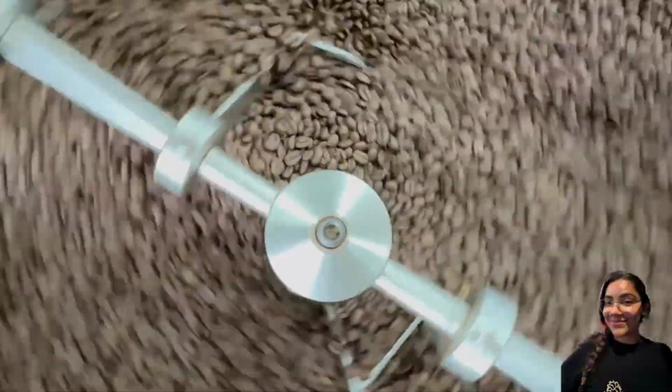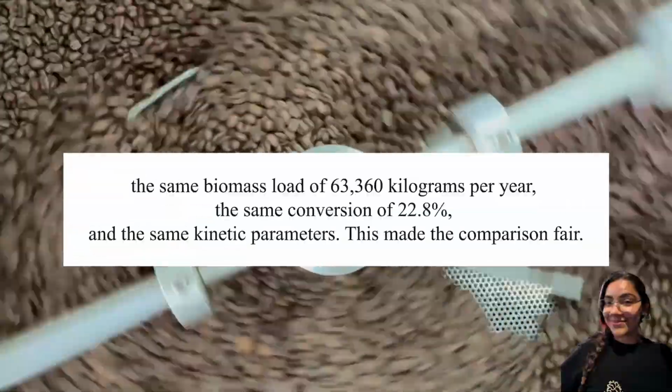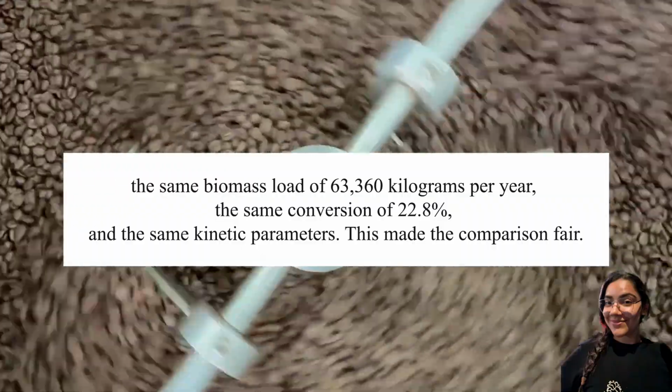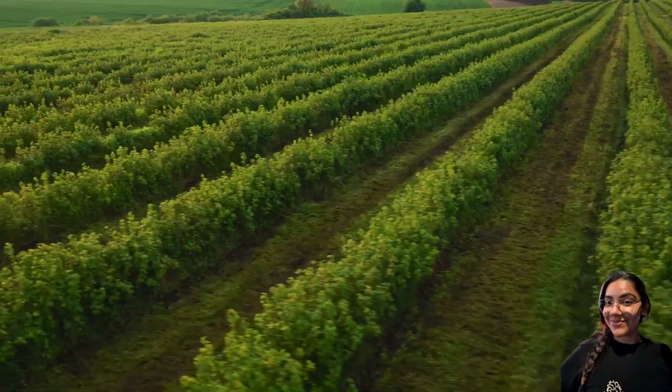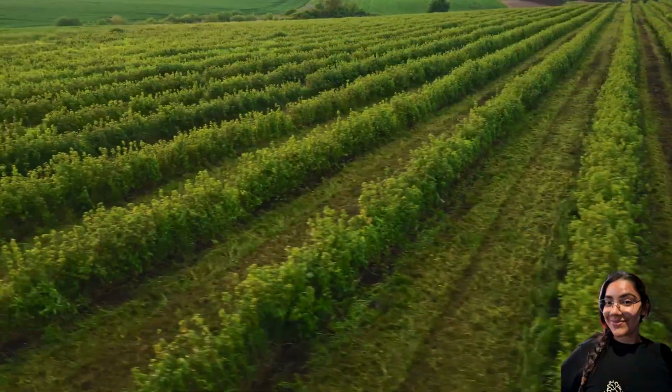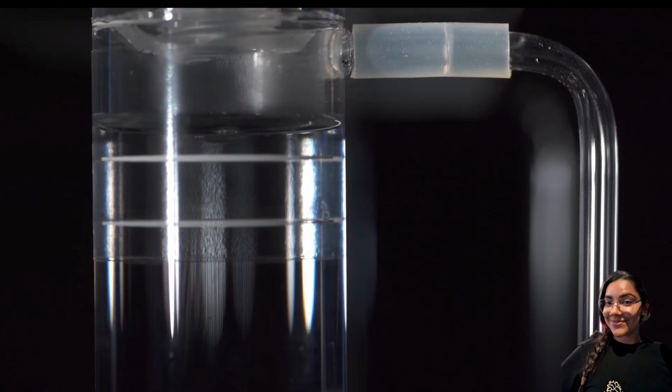We used the exact same basis for the three reactors: the same biomass load of 63,360 kilograms per year, the same conversion of 22.8%, and the same kinetic parameters. This made the comparison fair.